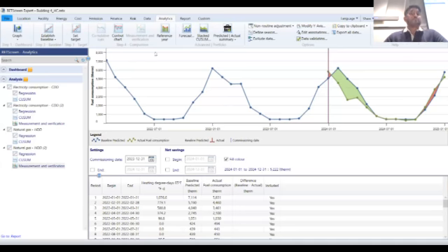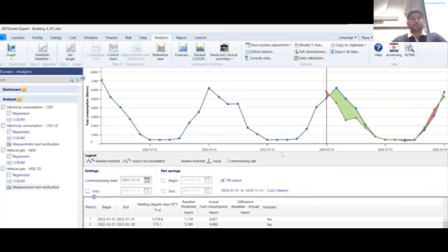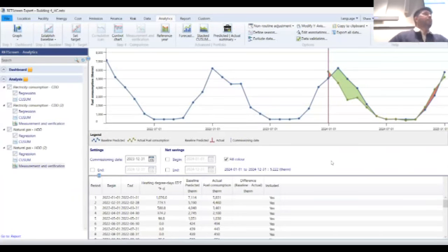Let's check how we did on our energy modeling part. We estimated 6,700 therms. So we overestimated our savings during our energy modeling exercise. We can go back and understand what we may have overestimated, and tweak something if we need to. That will help us get back to the actual number. This helps us understand that we were not very far off, but we still overestimated our natural gas. At the end of the day, we ended up saving 5,222 therms. So that's our natural gas savings.